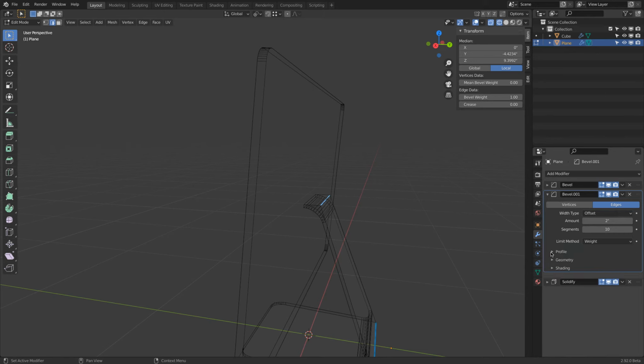So hold on. We go to here, geometry and clamp overlap. Clamp overlap, what does this mean? Basically, this means when there is a bad result happening, the software prevents you from rounding more. So we are actually at 0.5, and you see now with 1, this edge would need to be here, but it's not there. So the software tries to simply prevent you from making bad geometry, but also pay attention to at the bottom how, kind of like when we add a way to here, this one shrinks. So it tries to bevel this out.